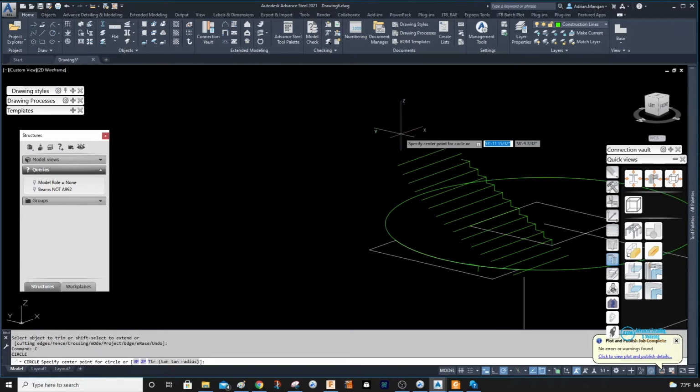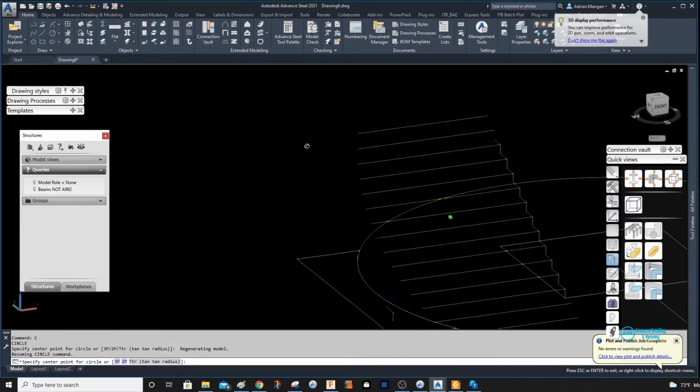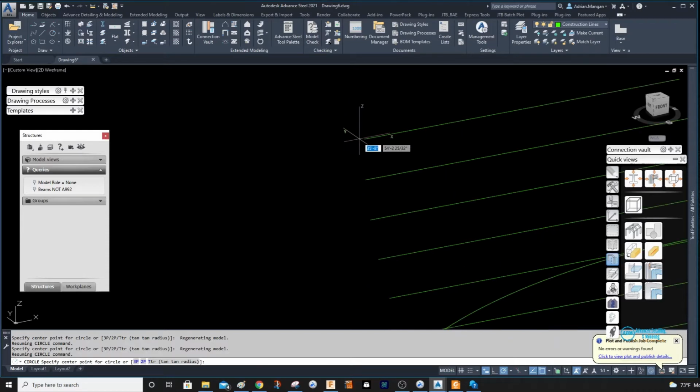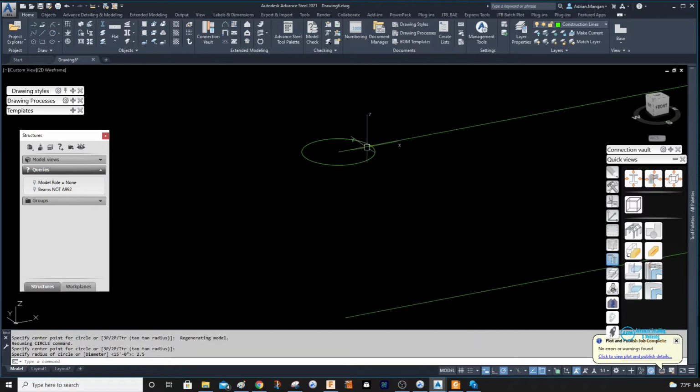So now what I do is I'm going to draw a circle here. So this is going to be the inside points of my stringer or wall, we'll say. So if I'm using a 1.5 inch schedule 40 pipe, it's like 1 7/8 inches. So for argument's sake, we'll call it 2 inches. So to the center, that would be 1 inch. So really it's 15/16 plus the 1.5 inch space, but we'll call it 2.5. So I'm going to do a 2.5 circle here. Then this point in here will be the point of the center of my railing.